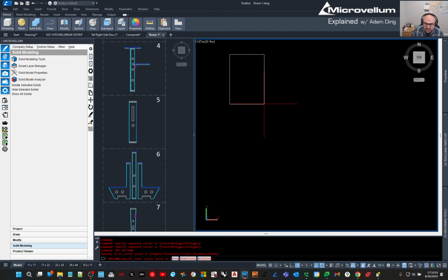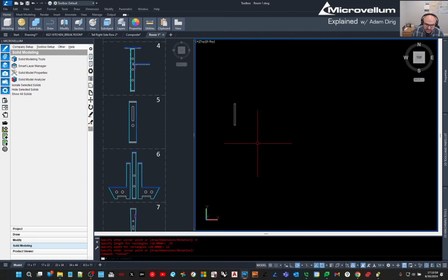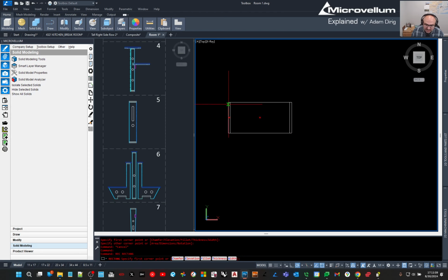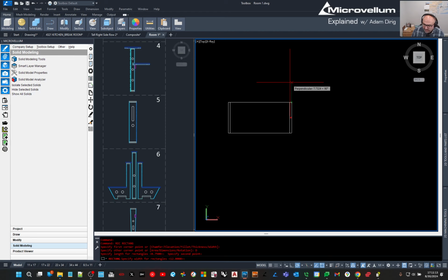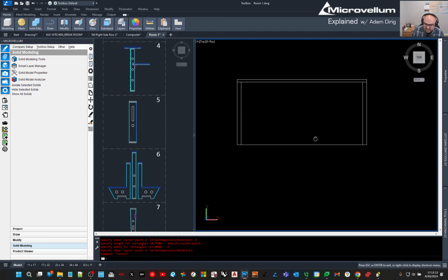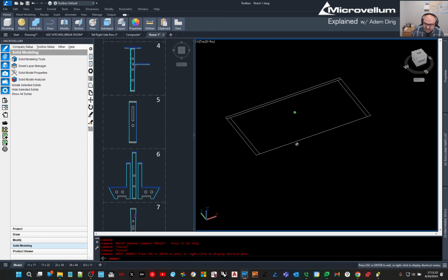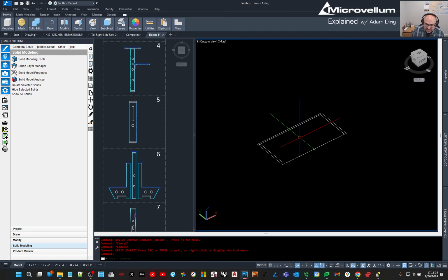So if I just start drawing a rectangle, I'm going to make it 3/4 by 12. I'm going to copy it, 24. I'm going to draw in a second rectangle that just kind of connects those. And one last one that's going to say, hey, it's this width by only 1/2 inch. So I've just done basically a plan section through a cabinet. I'm going to look at this though, and I'm going to say, all right, let's just add a little dimension to this.